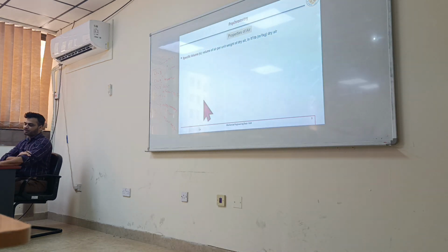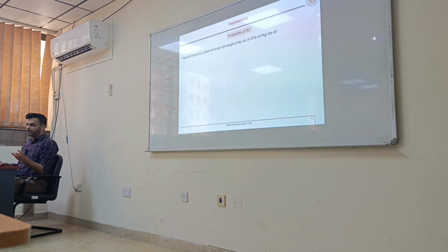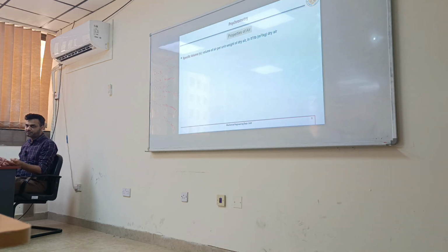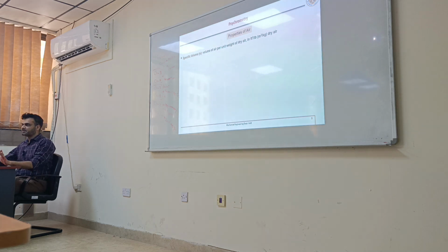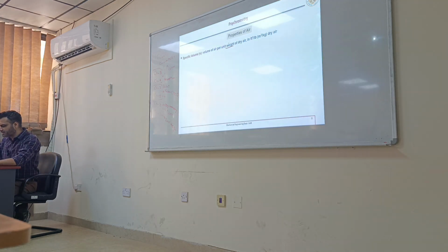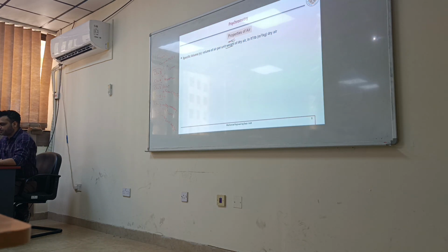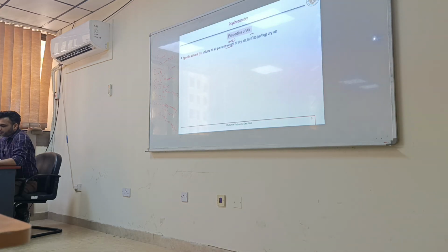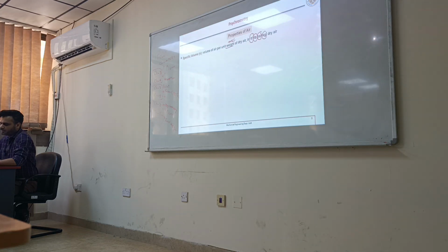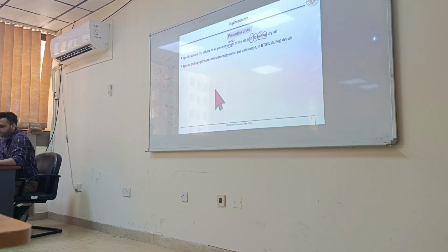So then there are some more terms. Now we have seen dry bulb, wet bulb, dew point, specific humidity or humidity ratio, and relative humidity. Next is specific volume. It's simple volume of air per unit mass. He's using weight, but actually it's mass. So volume of air per pound of air, or meter cubes per kilogram of dry air. That is called specific volume.